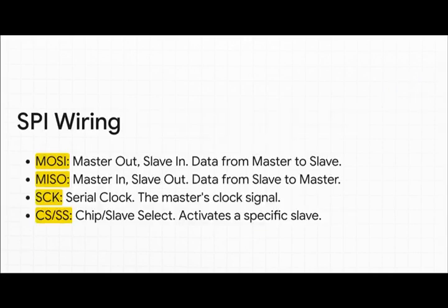Just like I2C, it has a serial clock, or SCK. But here's the big difference. Instead of one shared data line, it has 2 dedicated ones. You've got MOSI, that's master out, slave in, which sends data from the master.